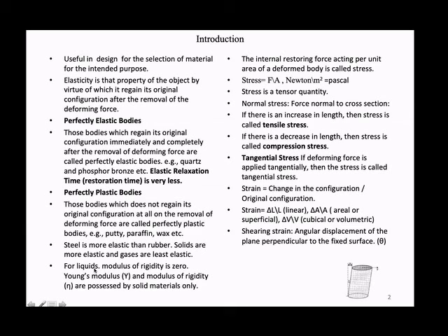See, for liquids, modulus of rigidity is 0. Rigidity means shear. There is no shear force in liquids. Some viscosity is there, but it's not a shear force. So Young's modulus and rigidity only apply to solid material. They won't apply to liquids. Okay? For liquids only bulk modulus is applied.